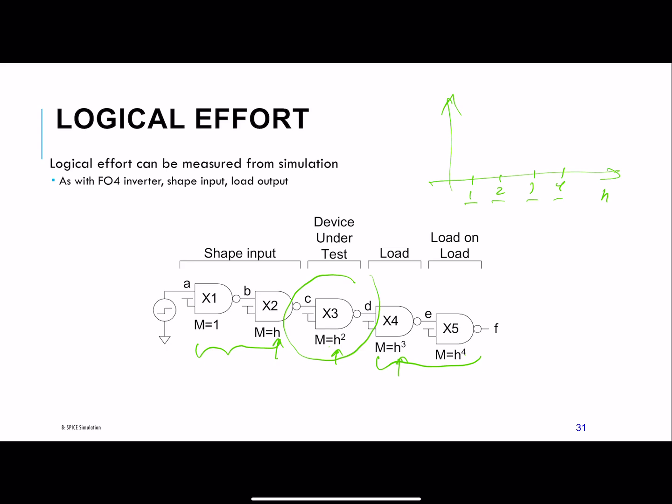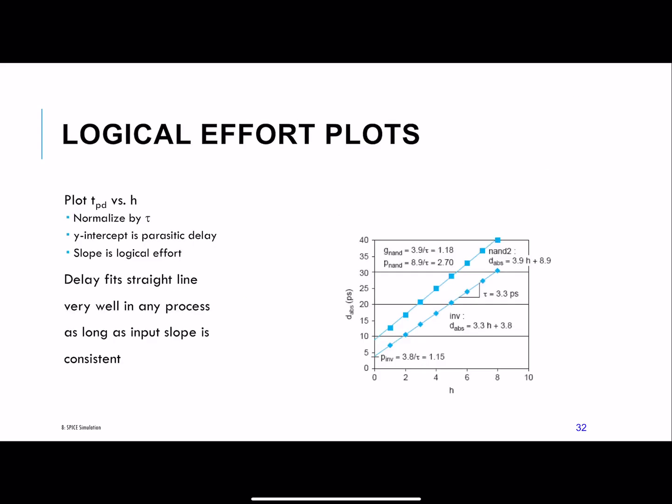You'll see this in my LT-SPICE tutorial video, how you do that. And then you can measure this delay and see how this curve changes. So you can get that curve of H versus delay for different devices, for an inverter or a NAND 2, etc.